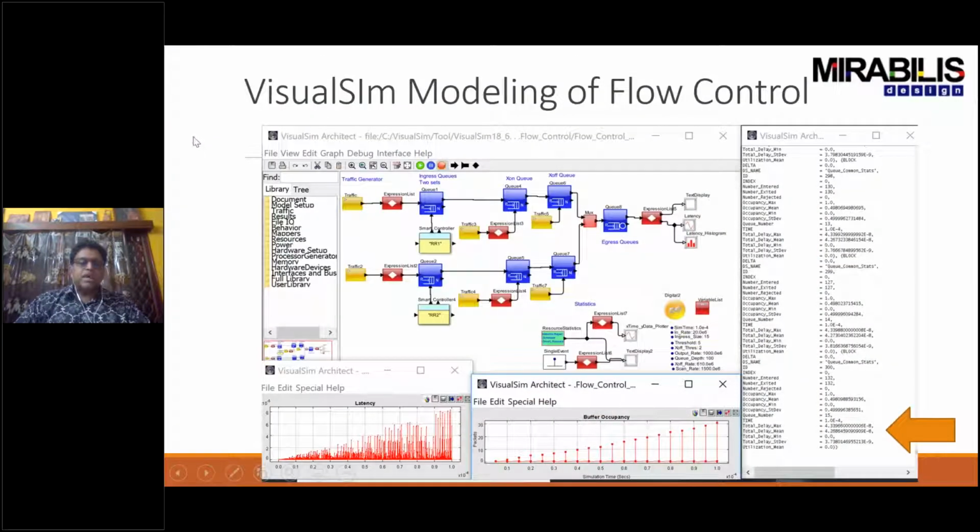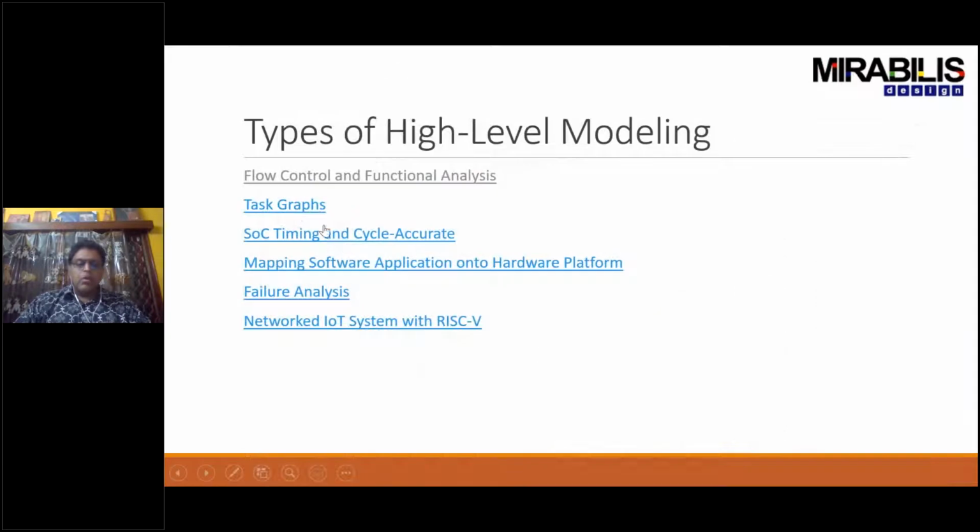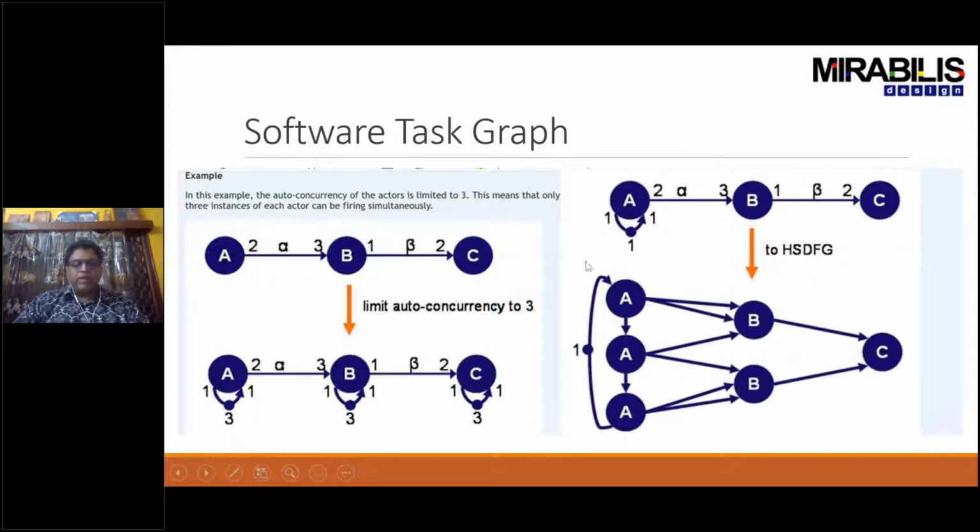As we go back to our design over here, we're now going to look at more details on the software, which is the scheduling algorithm. We're going to narrow it down there. This is the task graph. So what is happening is, just like you saw, we have A, B, C, 3 flows or 3 states. It starts off with state 1, has to have 3 instances of it, with each one generating certain tokens that are fed into the second stage, which both of them have a requirement of 3 tokens, and then each of them sends an output, and then the C has 2 tokens.